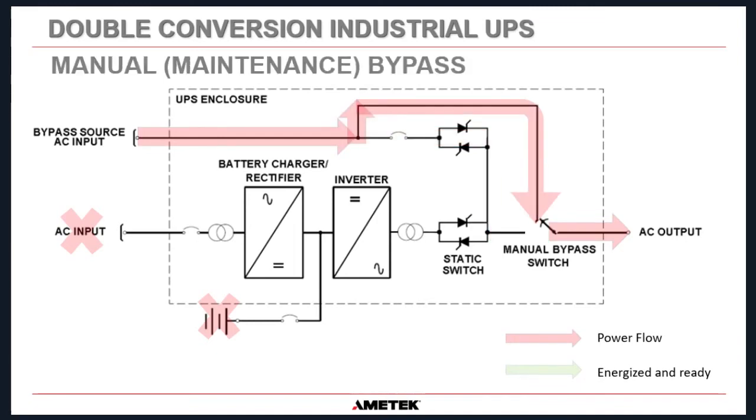And then in our systems, whether you buy a remote manual bypass switch or a standalone system that has a bypass switch on the front of the UPS, you will be able to go into maintenance bypass, which supplies power from the bypass and bypasses the static switch entirely through the bypass switch and allows you to do maintenance within the UPS system without there being any power inside there.